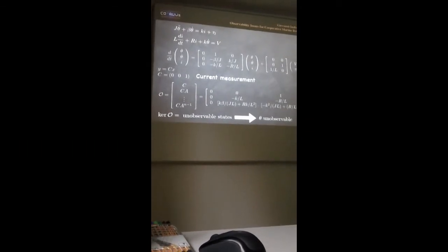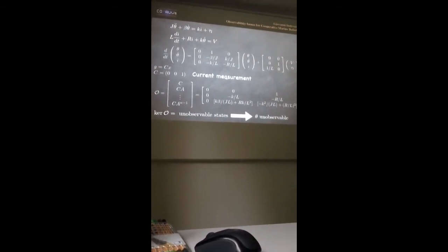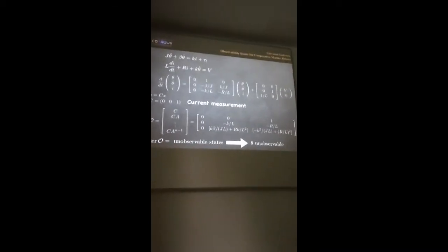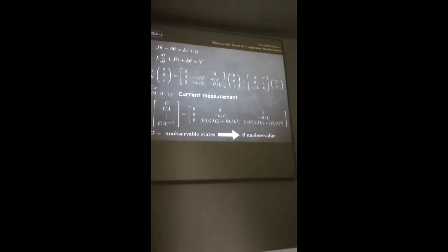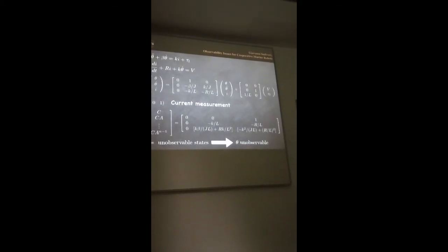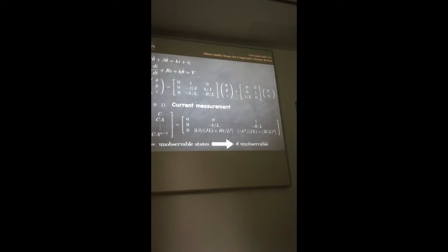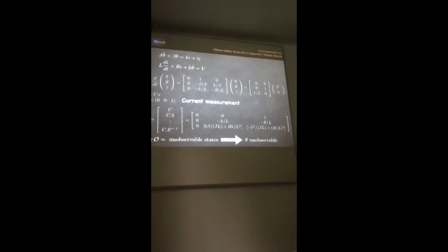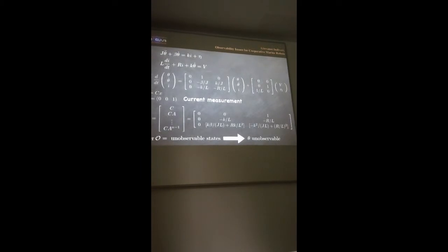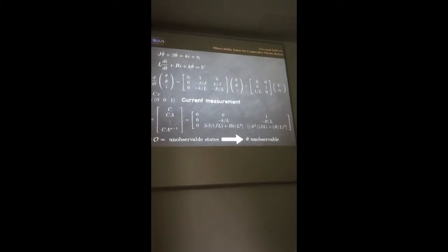And of course, you can do the same with measuring the currents. If you measure the current, this is actually very useful in underwater robotics. If your motor controller board allows you to measure, the fanciest solution is where you measure actually both the angular velocity of the propeller and also the current absorbed by the motor.